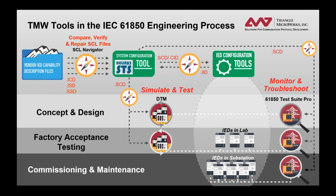So yeah, we've been referring to it as Distributed Test Manager. We actually have a lot of training and information on our YouTube channel as well, but the reason we call it Distributed Test Manager is because for large systems or for specific systems, you do need to distribute the load, right? Which means that we can take all of the devices that we simulated, instead of just doing it on my laptop like I did today, you can actually set up multiple computers and distribute the individual IEDs to each computer.